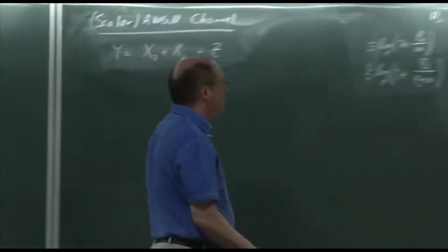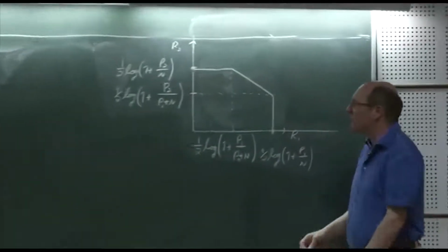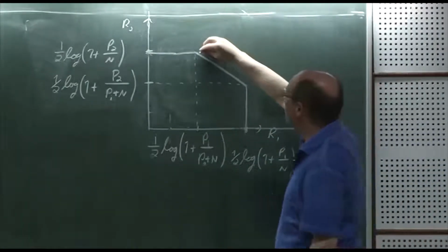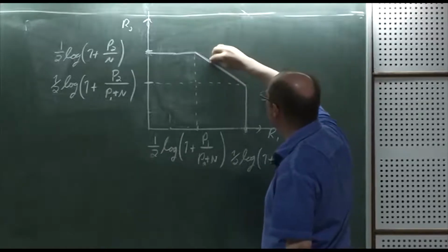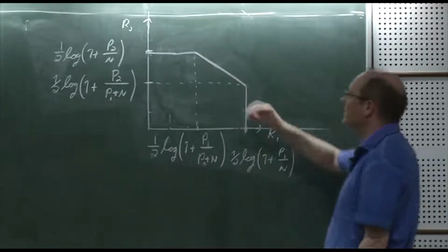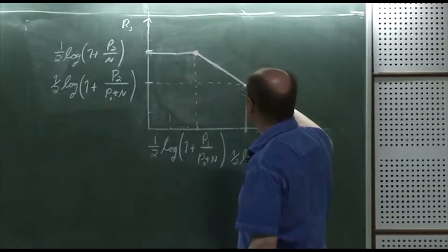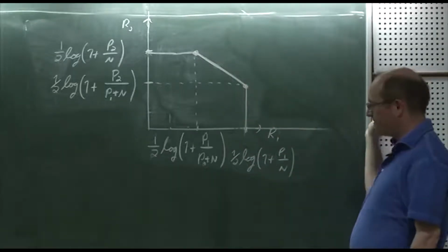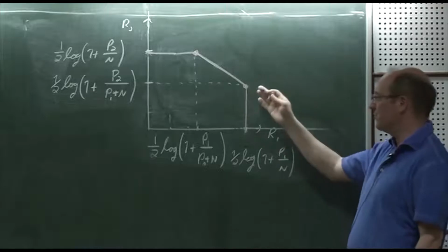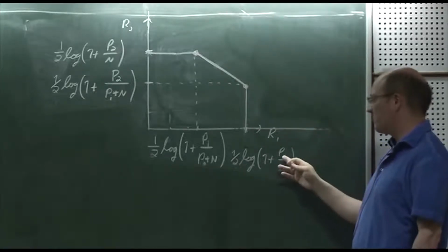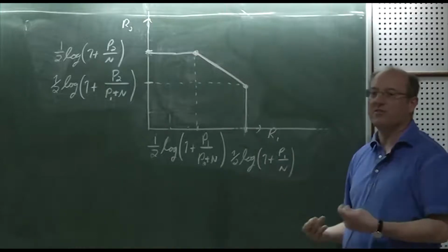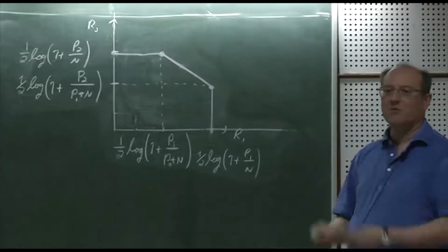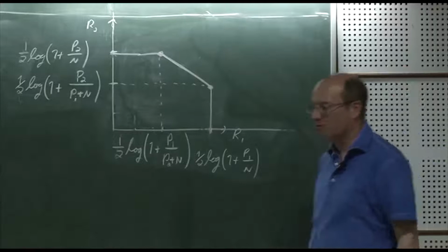We are talking about various achievable schemes for the very basic Gaussian channel. So the capacity region we said looked like this, and usually one is interested in approaching points on the dominant face. We said one point was here, one here. Then we gave an example where sometimes this pentagon is very skewed, especially if one user has much more power than another, and often in wireless channels this happens, right? So the SNR differences can be 20 dB or more. I mean, there can be extremely large differences.